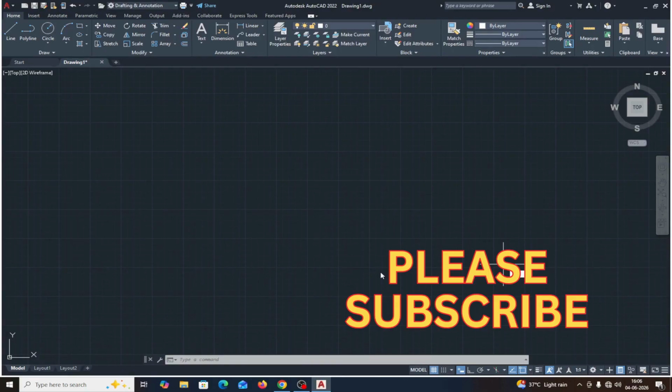Hello everyone, in this exercise of AutoCAD we will understand how to measure the distance, area, angle, circumference and radius of different objects. Okay, let's start. For this, in order to measure the distance, in the ribbon bar, in the utility section, you find the measure command. With the help of this I will use all of these: quick, distance, radius, angle and so on.